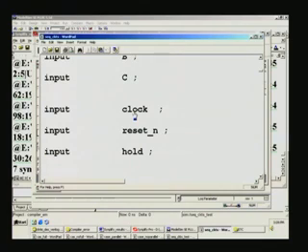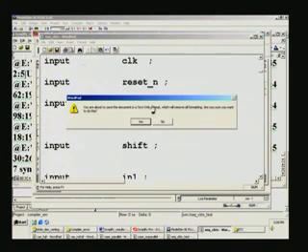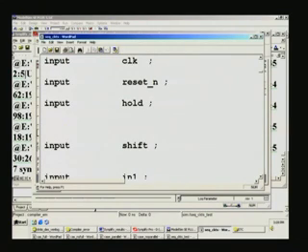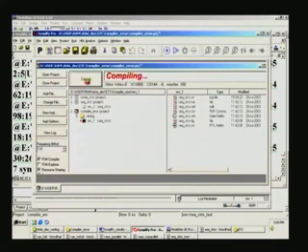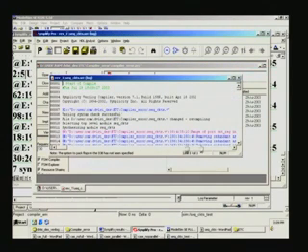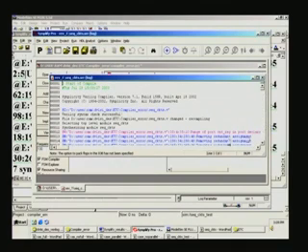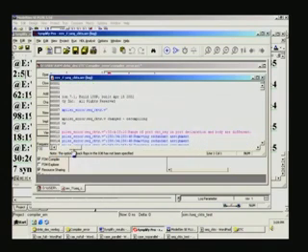That is because we have not corrected here. So, this error you should deal only with one error at a time. So, going back to Simplify Pro, let us run again. It has not reported any error this time, but warnings are reported. Let us see what the warning is. This is the warning here, and the warning says range of port counter reg in port declaration and body are